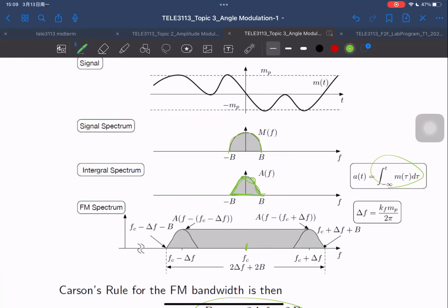So essentially you're going to have 4 pairs of spectral lines. You're going to have your FC, and a pair of them will be FC plus 40 and FC minus 40. Then negative FC plus 40 and negative FC minus 40. Because you also have another component, which is 90, you're going to have another pair.